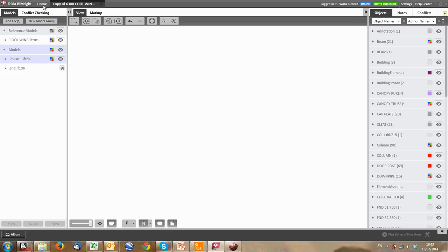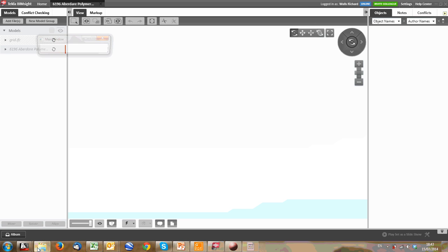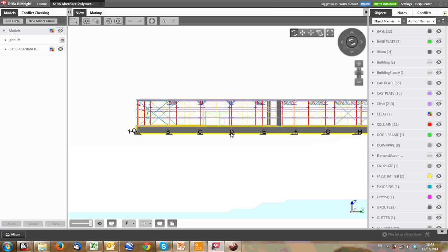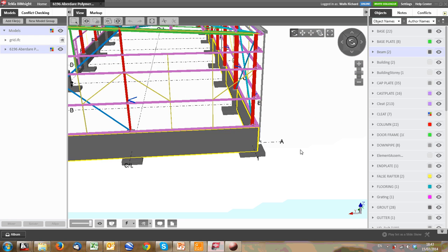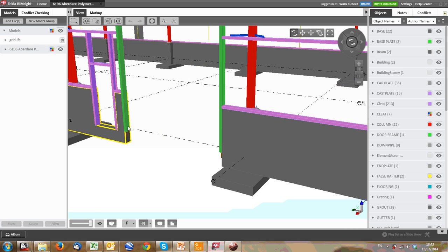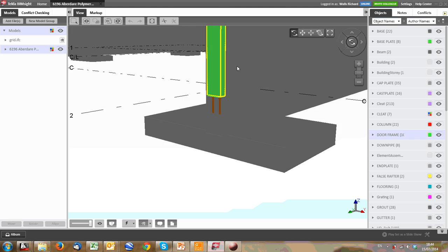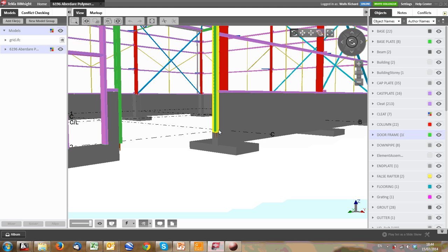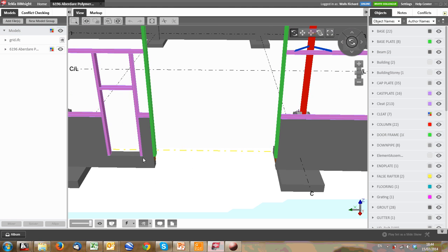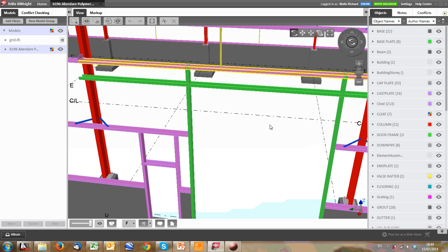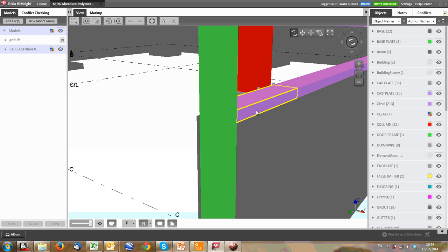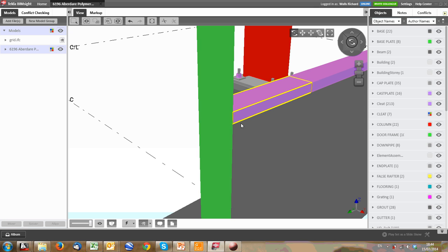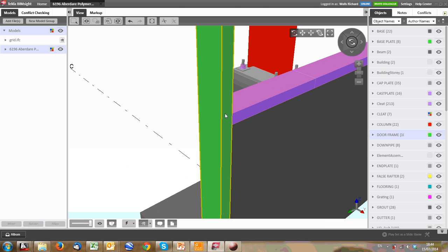I'm just going to go to my layout there. Right. Go back to my layout. Go to this side. There we go. There's your parallel flange channel that would be bolted to the surface bed or bolted to the foundation. You can normally chemical anchor this, so you can tie that and then make sure this line, just be careful, sometimes you want to tie this up with the front of the girths such that then your sheeting fixes to this.